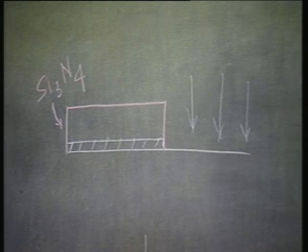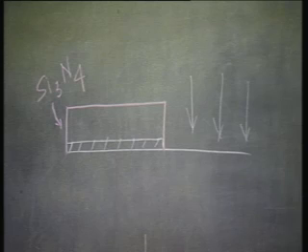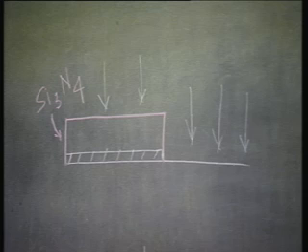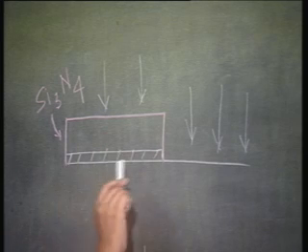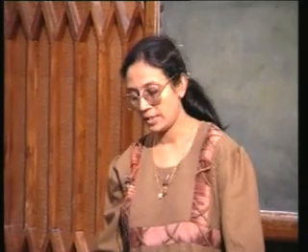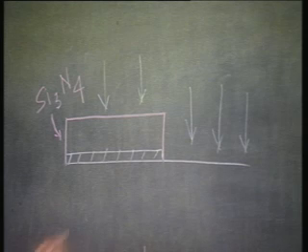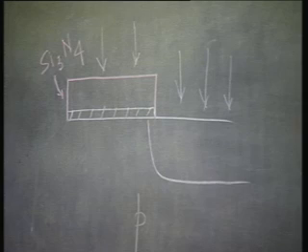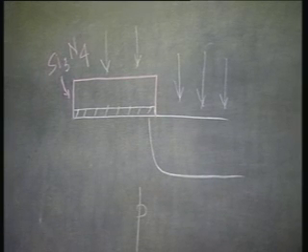Okay. So, you see this implantation can be a blanket implantation. Certain regions are protected by this silicon nitride, silicon dioxide mask. So, with this mask on, you can just put it on for a phosphorus implantation, right. And once you have the phosphorus implantation, you have certain regions doped N type.